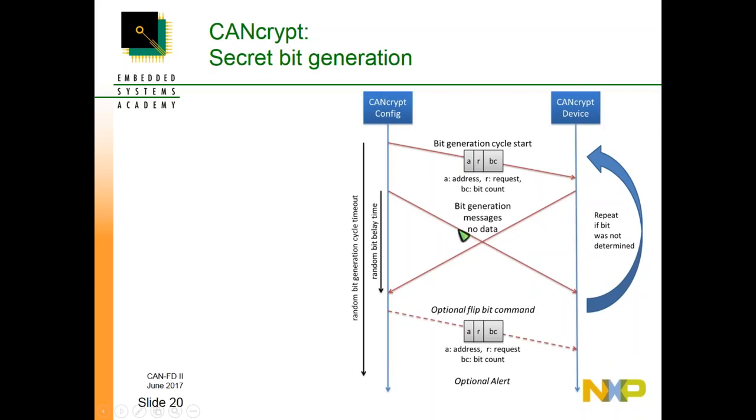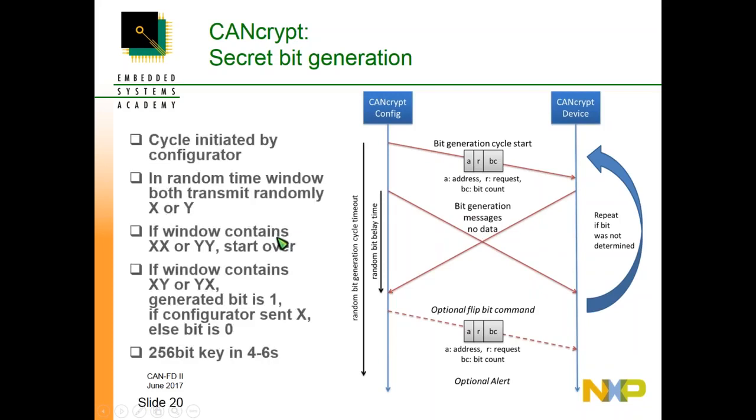The basic concept is that if you look at a CAN message and you only have access to the trace, you see which messages are exchanged, but you don't know where they originate from. If you have 10 nodes on the network and all of them can produce CAN message ID 1 and someone sends it, well, if you look at the bus, you don't know who sent it. However, if there are 2 nodes involved in a communication and they agree to only use CAN IDs, let's say 1 and 2, and they transmit something randomly with either CAN ID 1 or 2, then to the observer, you don't know who sent what. However, these 2 know what they sent and know what the communication partner sent. And from that information, they can derive a single bit.